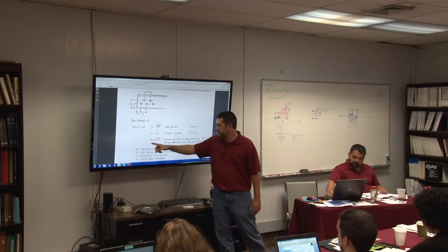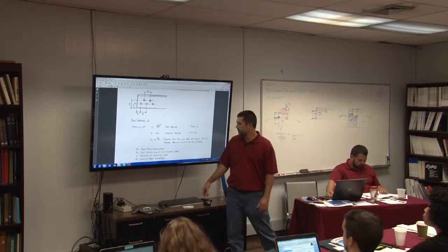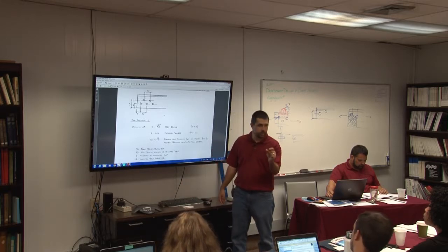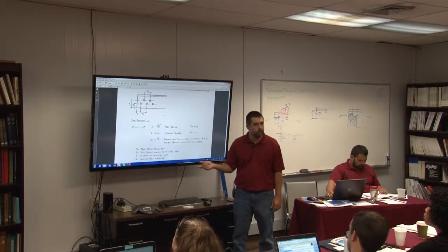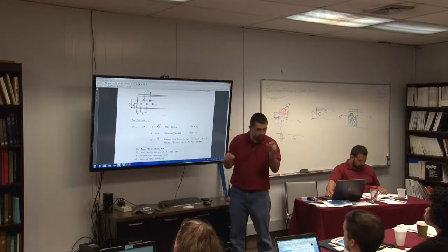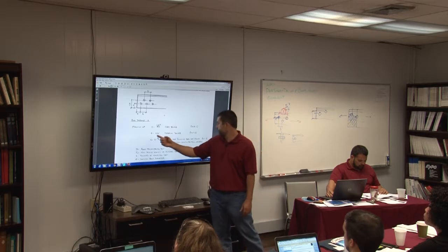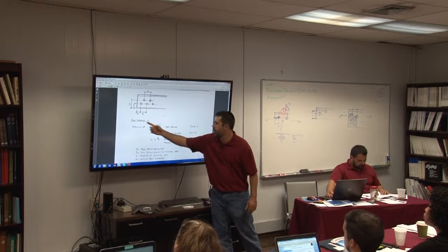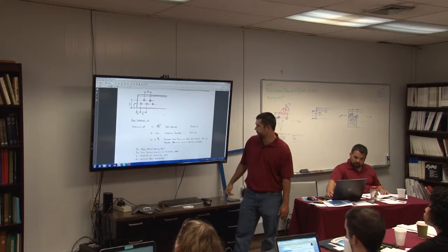Essentially, this limit is about fabrication. If the end distance is less than the thickness of your material, then you have problems when you punch the hole. So if you have a 1/2 inch thick material and you're trying to get the edge of the hole 1/2 inch from the edge of the member, you have problems doing that. So this is kind of a problem for punching. And then I'm going to talk about, again, the derivation of where this end distance came from.